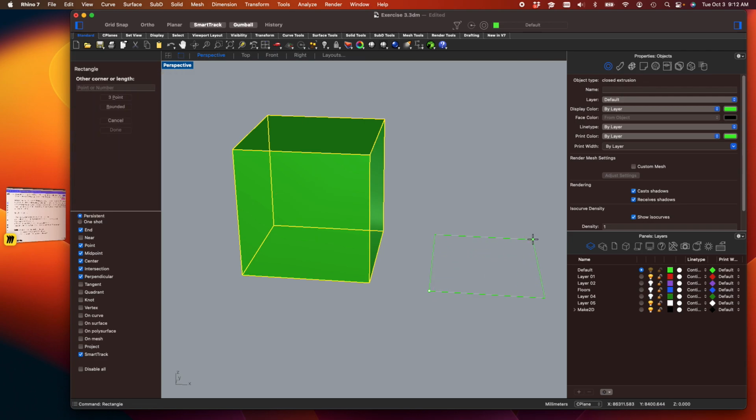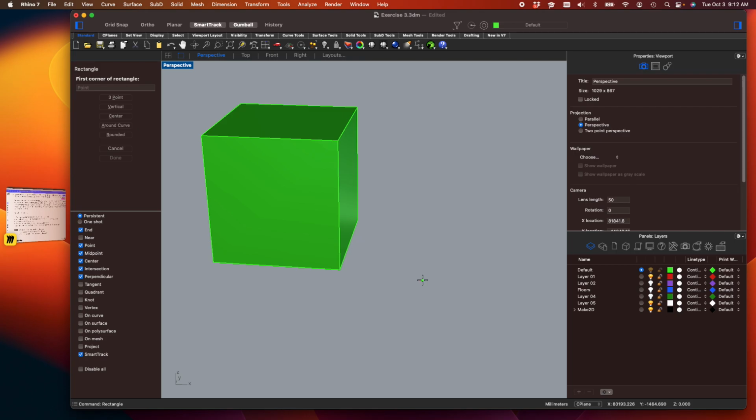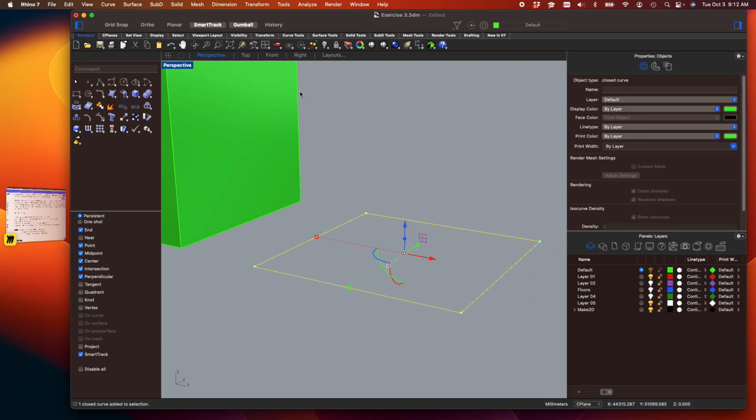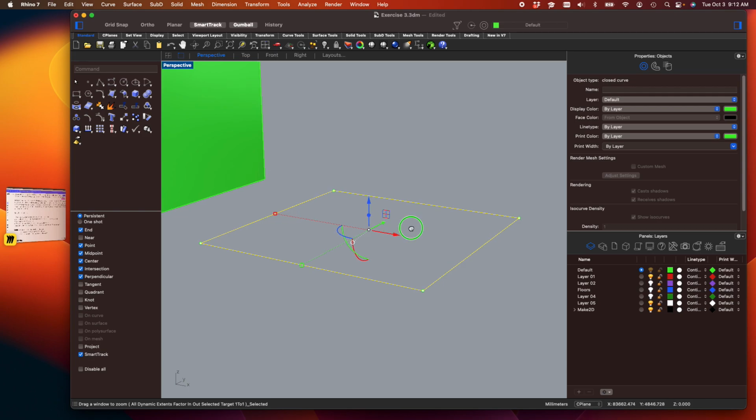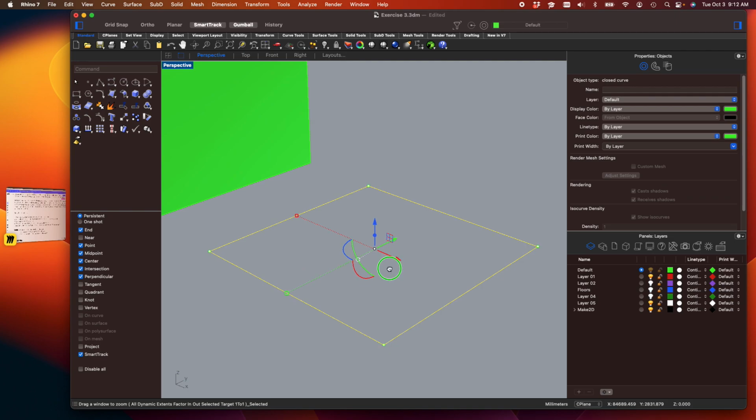So I'm going to go ahead and make a rectangle, 30 feet by 30 feet. Oh, I think I accidentally did 30 inches. 30 feet by 30 feet. There we go. So I'm going to make it inside this box. I do want to cover a couple of different ways to make some of these objects or sculpt them. First one, I'm going to zoom selected. Just in case you didn't know about that, guys, zoom selected is like your best friend, especially if you notice that you can't zoom in to your object that you want to work on.